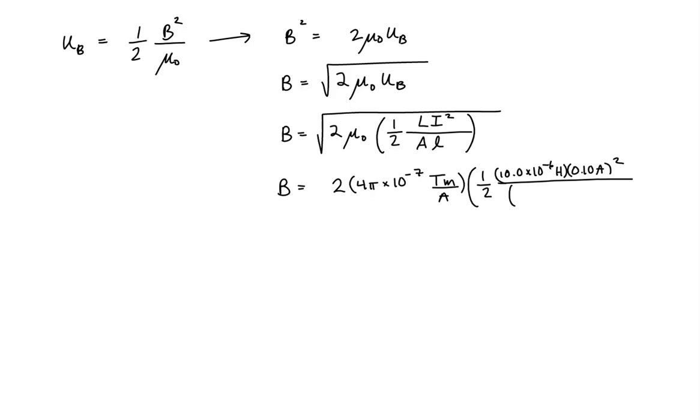The area of our inductor is pi times the diameter over 2 quantity squared. The diameter was 4 millimeters over 2. This quantity is squared. And this is times the length of our inductor, which is 5.7 centimeters. All underneath a square root.